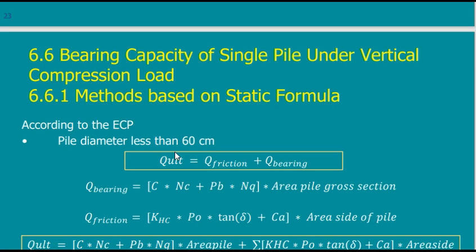But you will have to conduct a pile load test on site. This is the governing one for me, because anything you calculate is just an approximation. I will say that this pile will carry 200 tons. Then all my design will be based on 100 tons or 200 tons, whatever the number is. And then I go to the site. I may construct a pile exactly similar to the pile that will be used in my building, and make a full load test on this pile, and I load it till it fails.